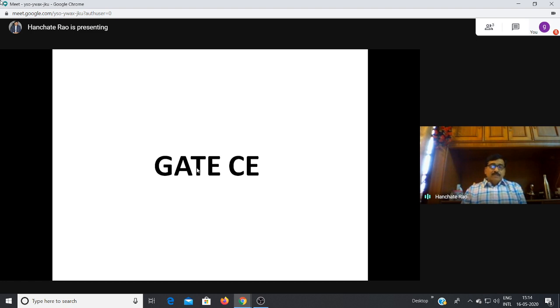Upward loading is possible whenever, for example, you are resting a foundation. When you rest the foundation beam on the ground, the ground reaction acts upwards on the beam. In such cases we get upward loading. Uniformly varying load in beams and arches: practically, uniformly varying loads you generally don't see. Mostly you get uniformly distributed loads in practice. In peculiar conditions we get uniformly varying loads.